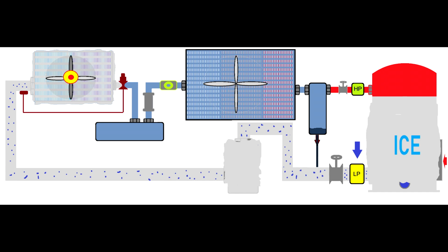If you have a heat exchanger that runs on negative temperature, the ice will build very fast on that evaporator. So you have to be very careful to have a clean evaporator and to apply the correct defrost, otherwise you will have this bad phenomenon and you will lose system efficiency.